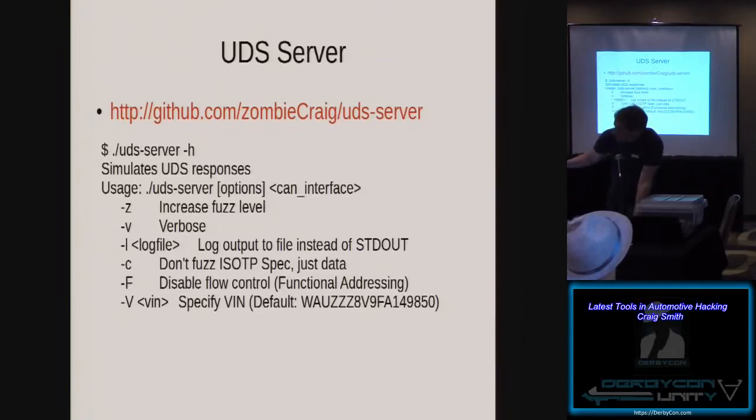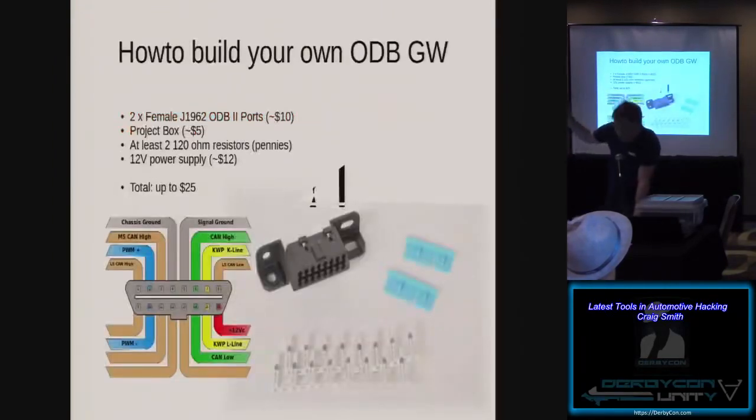And all it really is, you have two OBD ports attached to it. What you have to do is, this is kind of the minimum install. You would run the ground wires to each other, the 12-volt power, and then the green one, so the CAN high, CAN low. That's the minimum. You will have to put a 220 ohm or 240 ohm resistor on the CAN lines for it to work.